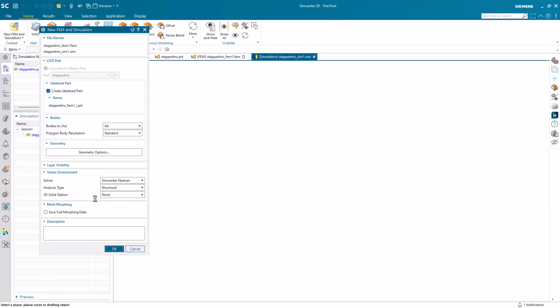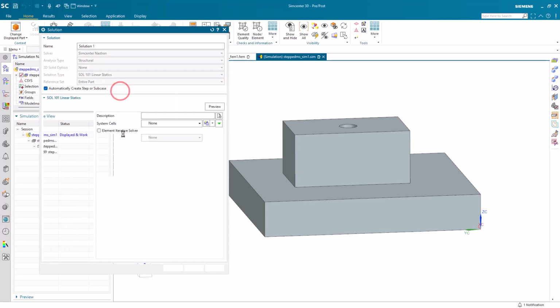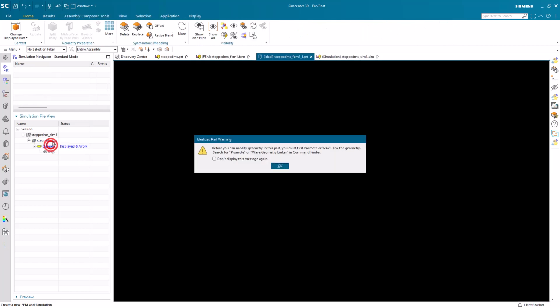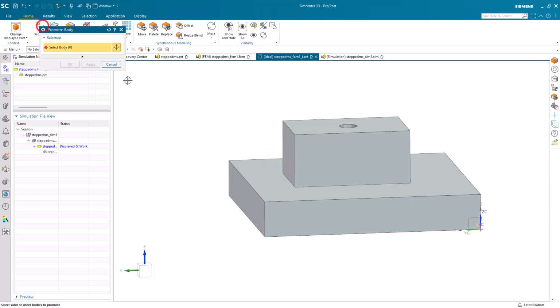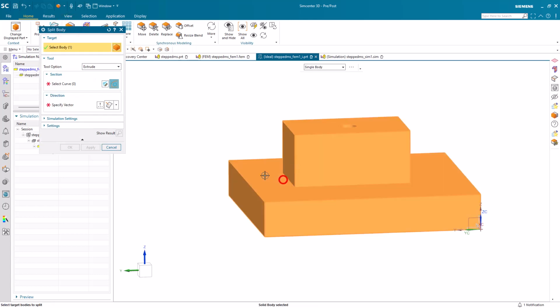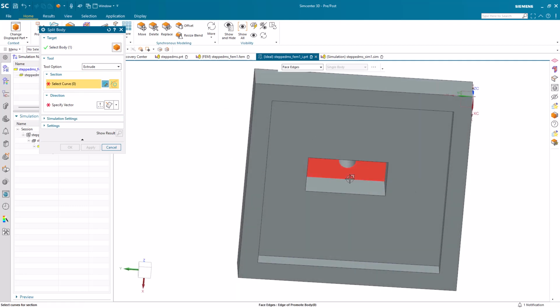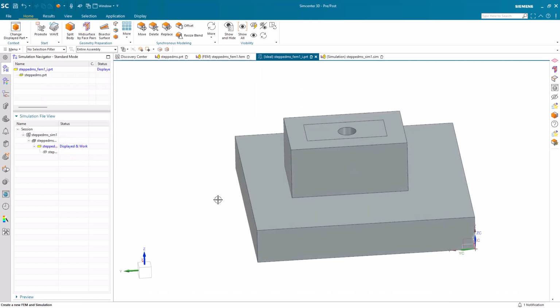Today we'll be creating a planar mid-surface on a stepped cover with the new Midsurface command that was introduced in version 2206. We'll begin creating our simulation files. Then we'll get an associative copy of our geometry in the idealized part. Next we're going to split our stepped cover with the face edges of the face of the top of the cover.